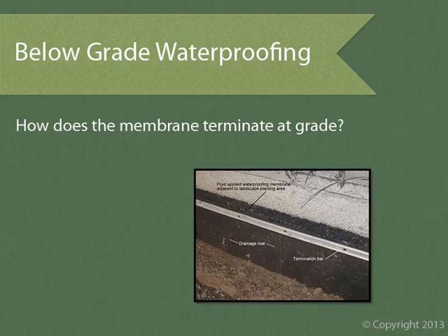Be sure to address this with your skin coordination program to ensure the actual products the subs are using do in fact work together to provide a constructible and appealing finished condition. For instance, one problem you might run into is the bottom anchors for the facade system conflicting with the membrane termination bar as you see here. A termination bar might be 1/4 inch thick, which is actually a big obstruction when it comes to situations like this.